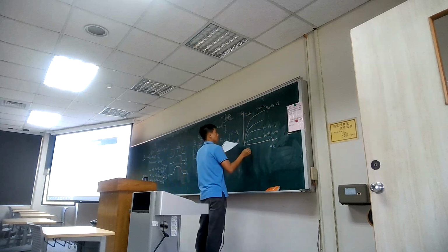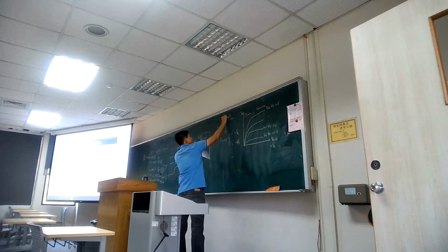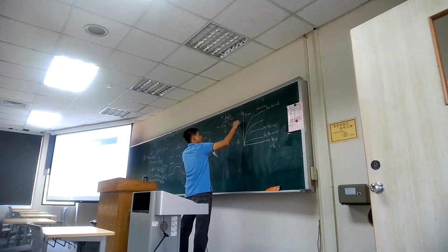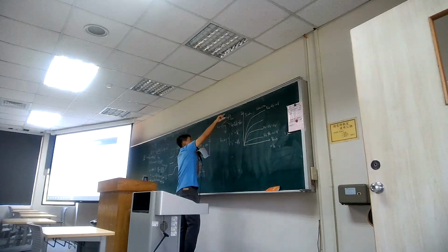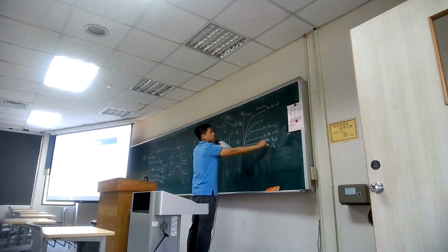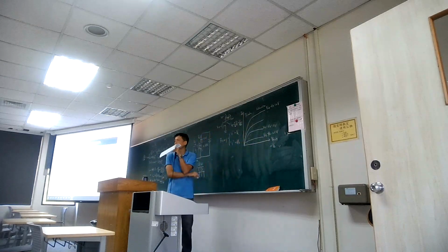potentials. So we can start with the load line. So what is the load line? What is the relation of the RD? So the load line will depend on VDD minus ID multiplied with RD equals V out. Okay. So the voltage supplied here minus the voltage drop along the RD equals the output voltage. So what is the relationship here? So we get ID, we get the V out as these two factors.